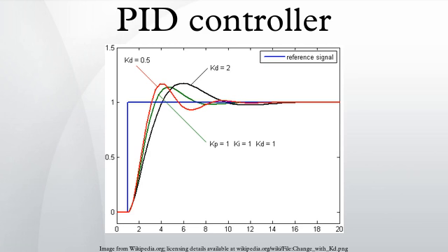Overshooting from known disturbances. For example, a PID loop is used to control the temperature of an electric resistance furnace where the system has stabilized. Now when the door is opened and something cold is put into the furnace, the temperature drops below the set point. The integral function of the controller tends to compensate this error by introducing another error in the positive direction. This overshoot can be avoided by freezing the integral function after the opening of the door for the time the control loop typically needs to reheat the furnace.